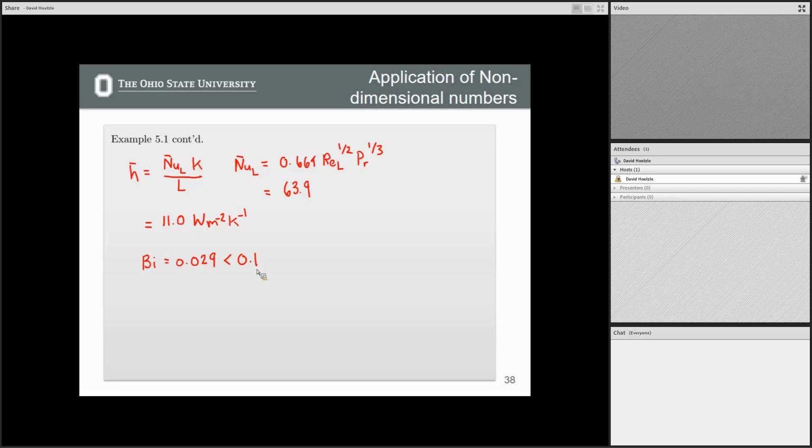The main message, and this is the main argument for a lot of work in powder bed fusion, is that they ignore convective heat transport. On Thursday we'll go through the nuance of where we do and do not consider convective heat transport. In terms of convective heat transport into the surrounding fluid, the air or argon gas in the chamber, oftentimes we neglect that.